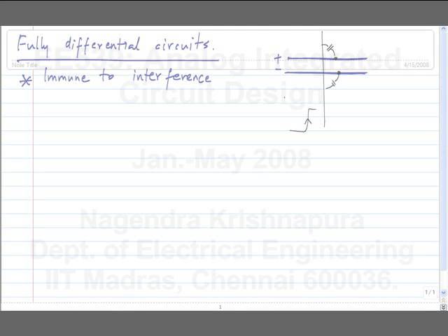For instance, if we had a single line like this, if the signal of interest was between this point and some ground. Now, the definition of ground is fairly difficult in any circuit, okay. It's supposed to be the common node, but you don't have conductors with infinite conductance. You will always have some resistance. So, there is no such thing as a single node. For instance, I draw a circuit with this thing at ground, something else at ground, and so on.